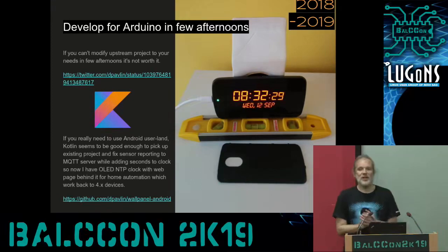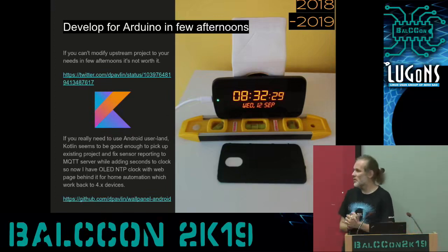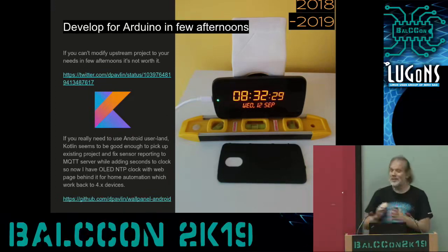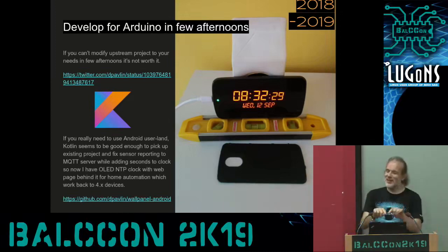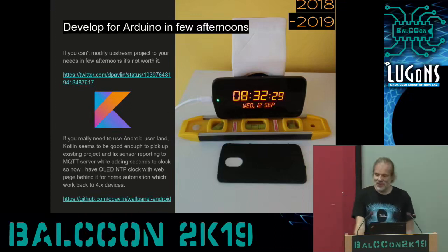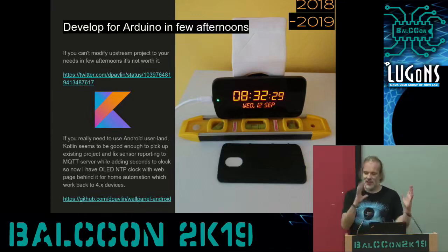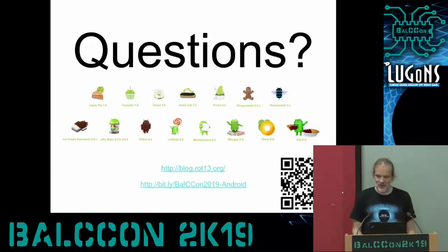In this project I learned that OLED displays really do have burn-in. When you have the same digits in the same place, it will change color after a while, like 3 months. When I put up a white background, I can see the numbers, which are light green because the reddish parts were burned out. This was the reason I decided to change the software to something which can move the clock over the screen so I don't get the burn-in.